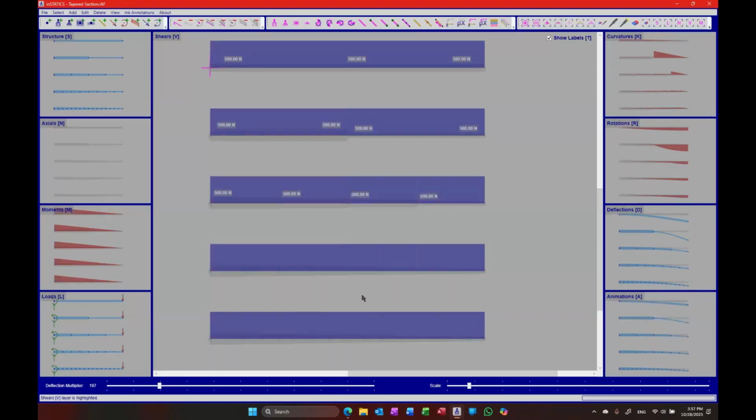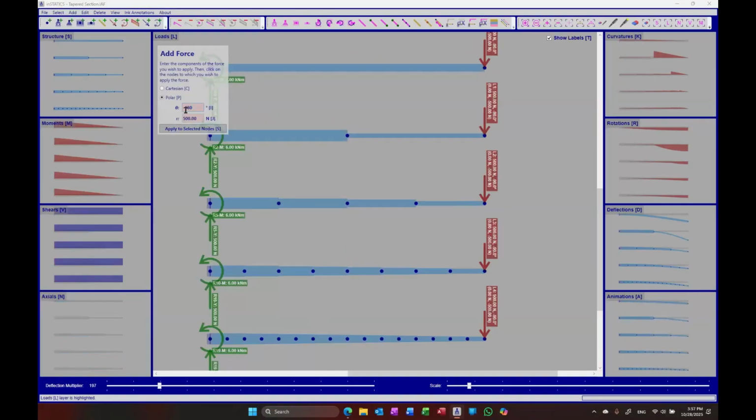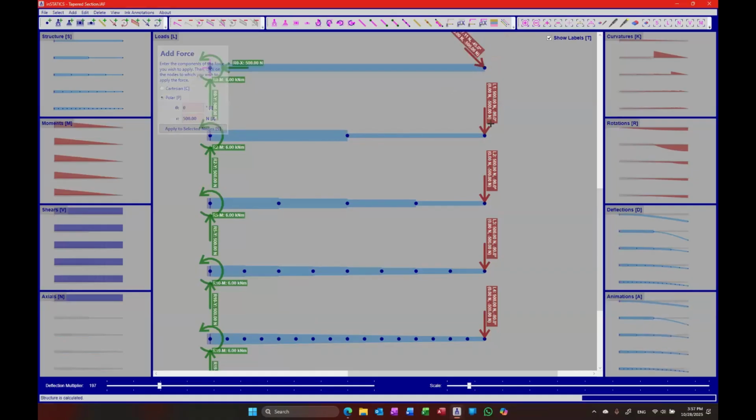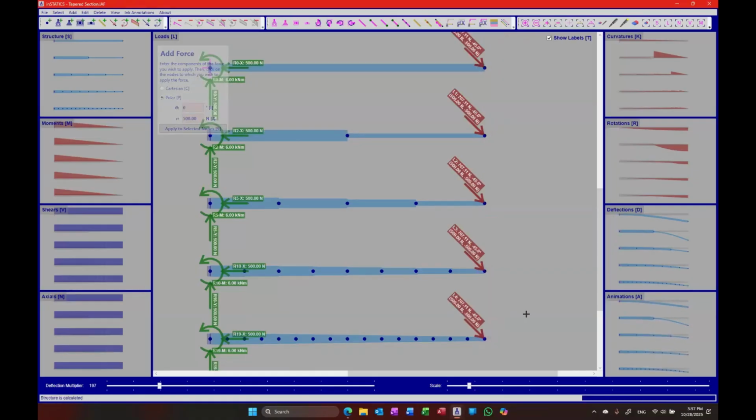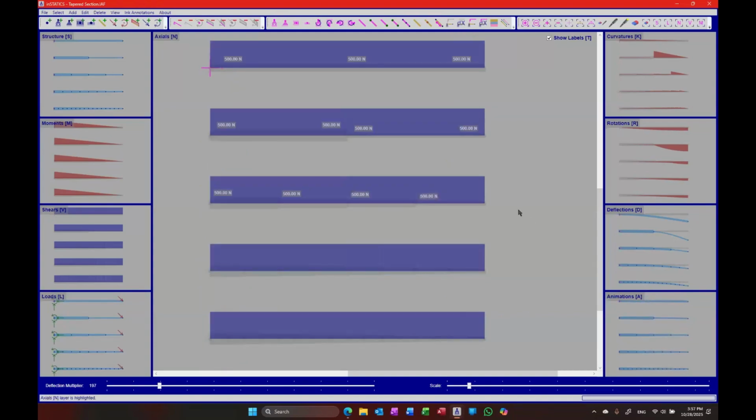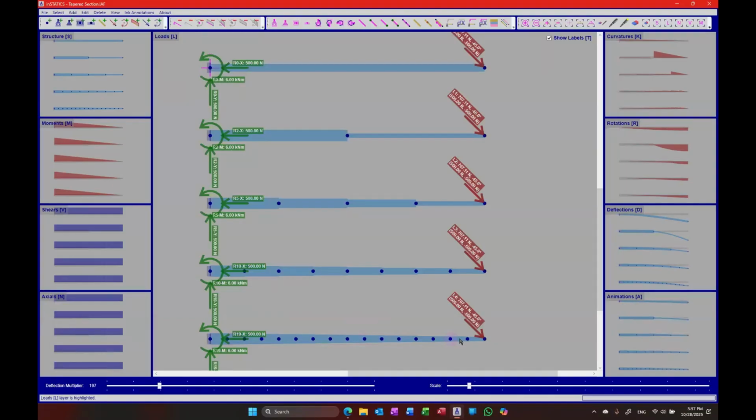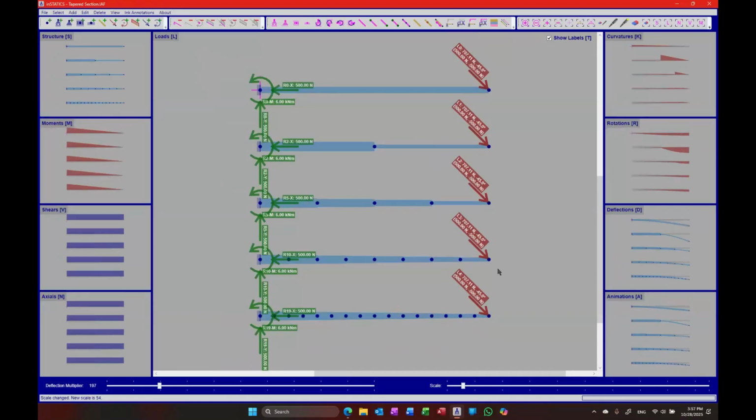The same thing here in the shear moment. We don't have any axial loads, but I could add a little bit if you want, and you'll see that it will be the same for axial loads as well. So there will be no difference because it is determinate. But if it is indeterminate, well, good luck, figuring it out without using this. It would be really, really difficult, I assure you. So this is another, quote unquote trick to use the power of the computational approximation to simulate more complex behavior.